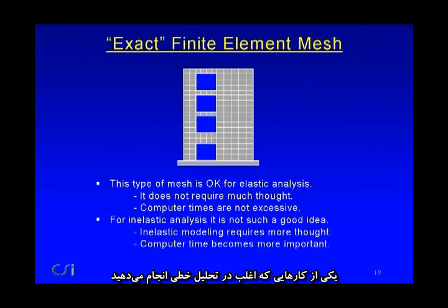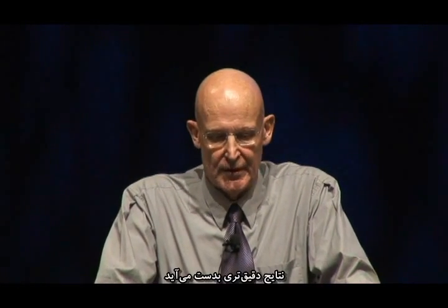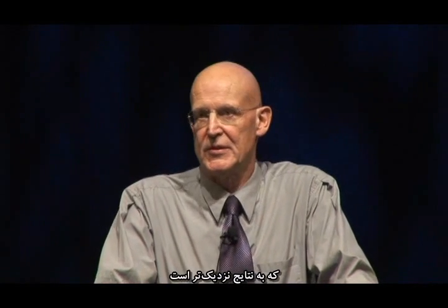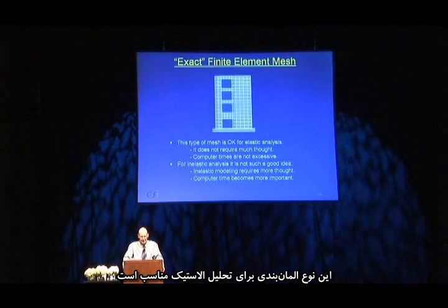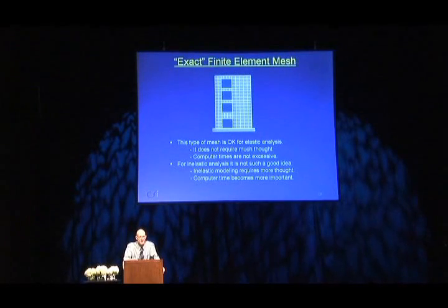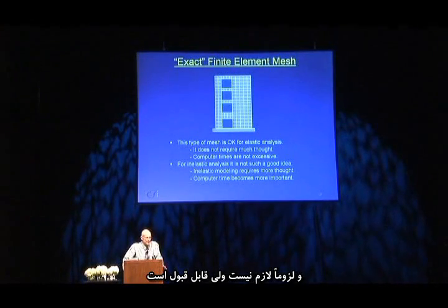Now, one of the things that you will often do in linear analysis is to use a nice fine element mesh, based on the idea that for linear analysis, the finer the mesh, the more accurate the result, or the more closely the result approaches an exact analysis for an elastic material. And this type of mesh is fine for elastic analysis. It's not necessarily necessary, but it's okay.